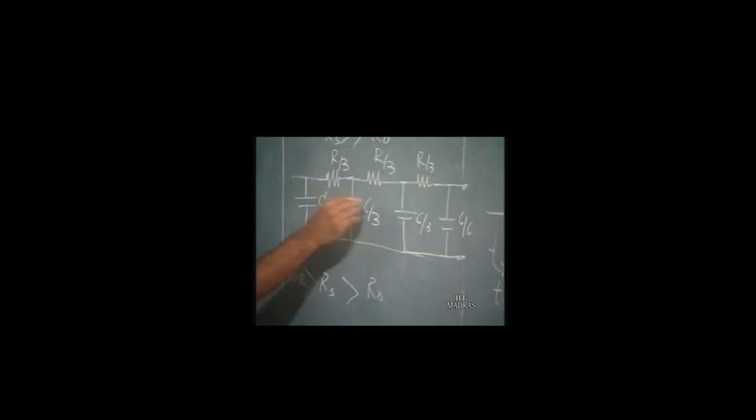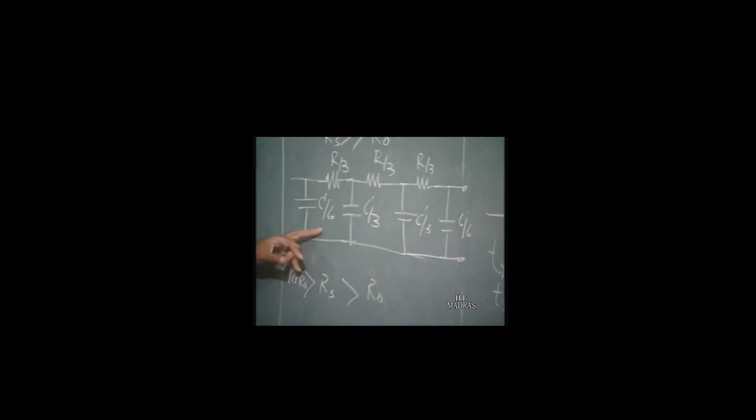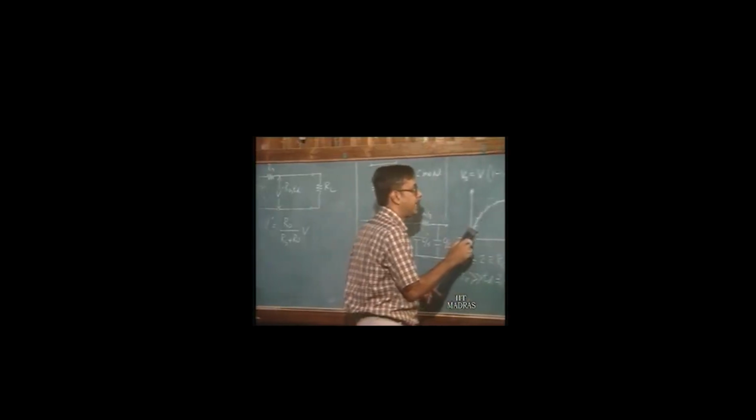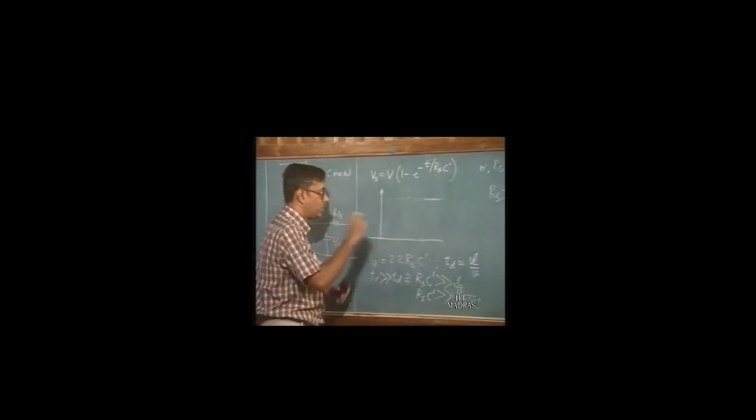So basically we do not have a single resistance and capacitance, but this is distributed, and we find that this gives more accurate delay values for the line. In fact, if we take the lumped value, that is only one resistance and one capacitance, it is going to be something like this. This is for lumped.